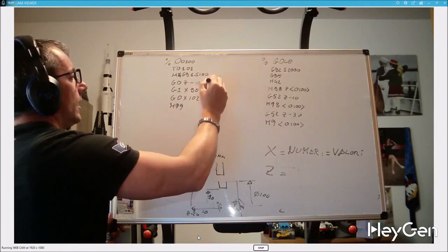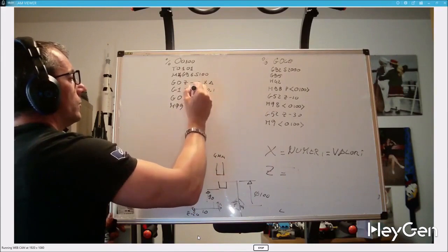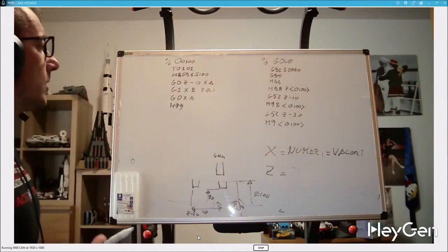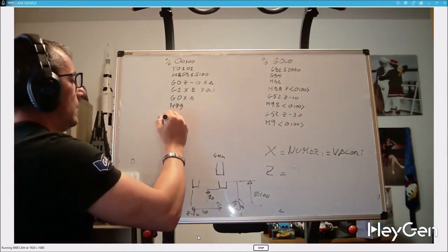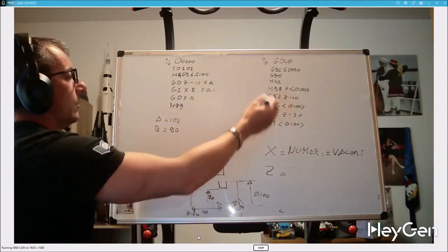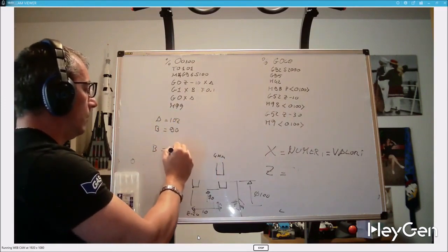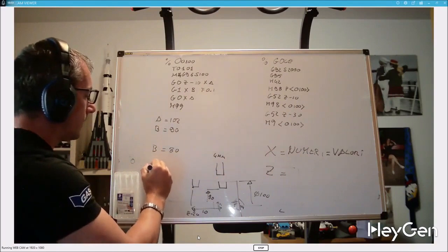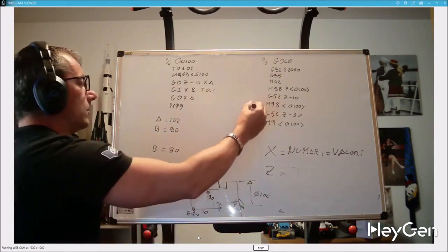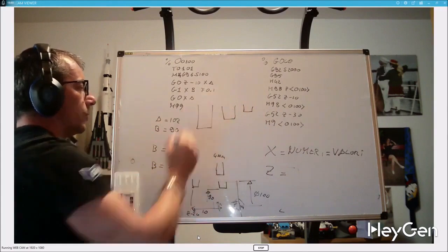That X102 is, do you see, A, and X90, that is the groove bottom, is B. Before calling the subprogram, we could set A equal 102 and B equal 90. When we call the second subprogram, we could tell it that now B is 80. When we call the third subprogram, we could tell it that now B is 70. So we'll have a groove like this, a groove like this, and a groove like this.